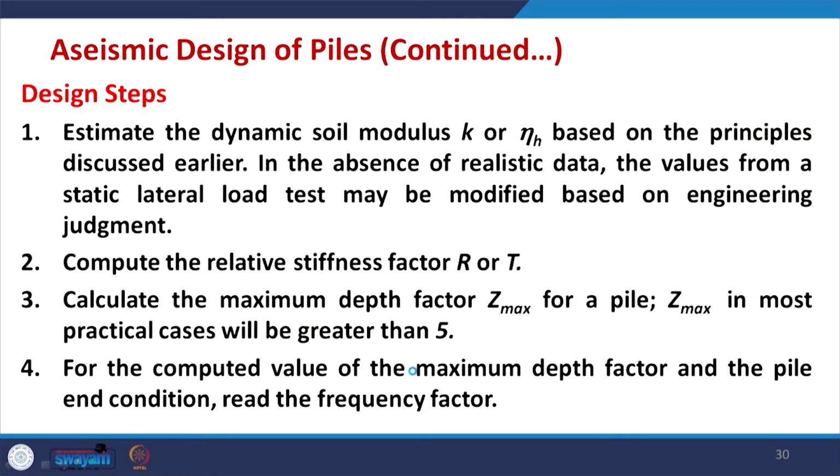Then continue with the seismic design of piles; these are the design steps. Estimate the dynamic soil modulus k or eta h based on the principles discussed earlier. In the absence of elastic data, the values from a static lateral load test may be modified based on engineering judgment. Then next, compute the relative stiffness factor R or T and calculate the maximum depth factor Z max